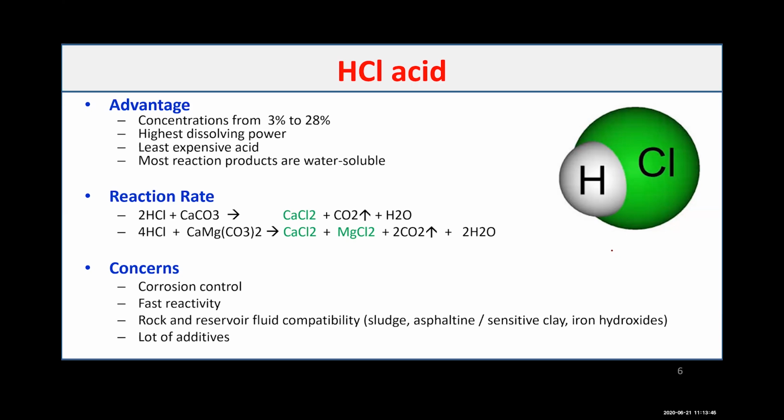So you have a broad range of concentrations that you can use. HCl is delivered to the field at a concentration of 31%. So that is the way that you start with it. You get it in the field at 31%, and then you can dilute it with water to the percentage that you'd like, based on the applications that you are recommending.